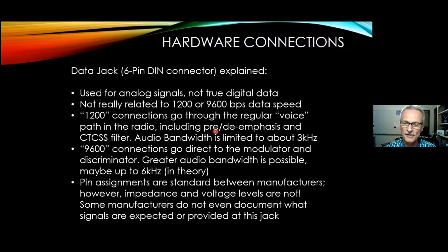The high frequency audio gets boosted by 3 dB per octave, and then on the receive side we go through de-emphasis. So we reduce the high frequency by 3 dB per octave, which means that we're going to bring the level back to where it should be, but we're going to be dropping the noise or the hiss down below that. So it works very similar to Dolby transmission, Dolby encoding and decoding on tape.